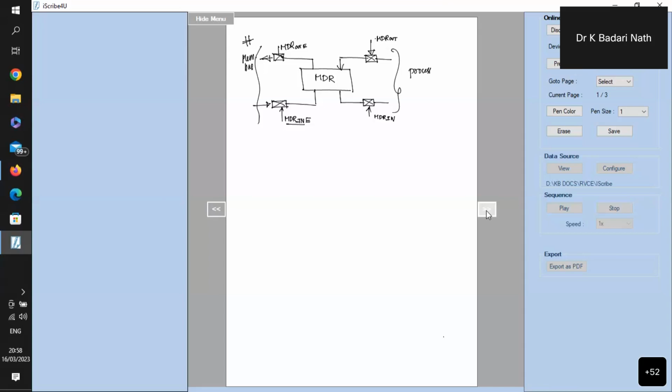So let's go back to the ALU section. In the ALU section, we have the ALU with inputs A and B available. Here we have the Y register. Y is connected directly, but the input to Y is through a control, called Y in. So another control signal is Y in. Whenever I enable Y in, only then will the data be written to the Y temp register.